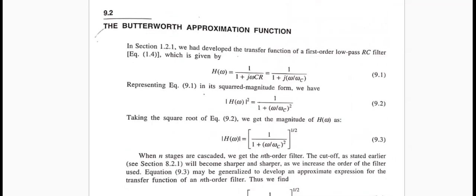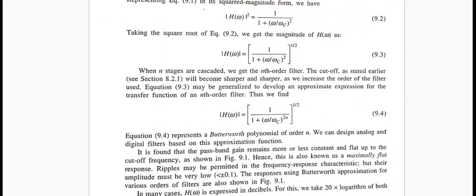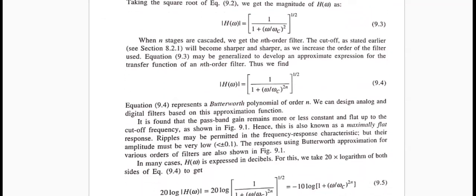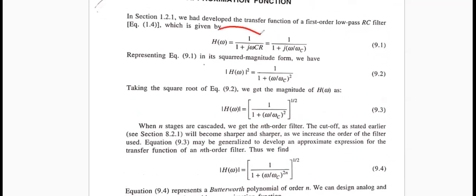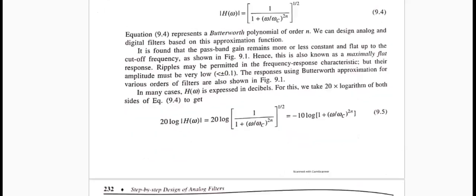Mostly we talk about the Butterworth approximation. If you can remember, we have already developed this equation for the nth order filter. It comes from the very basic first order filter. We start from scratch with the first order filter, and we generalize that for the nth order filter.